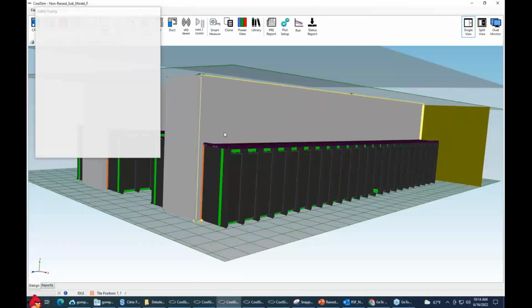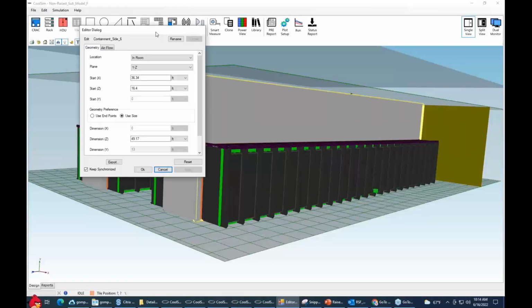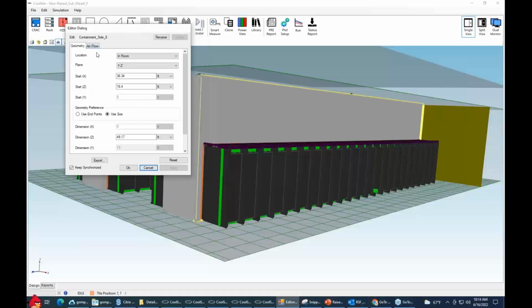I do that intentionally because a baffle is a very low-cost CFD element. It is a zero thickness partition on the mesh. A little bit more information than you need to know, but in this case, it's just really easy to use them. They're inexpensive from a computational point of view, and they allow leakage. So that's a nice thing about it.